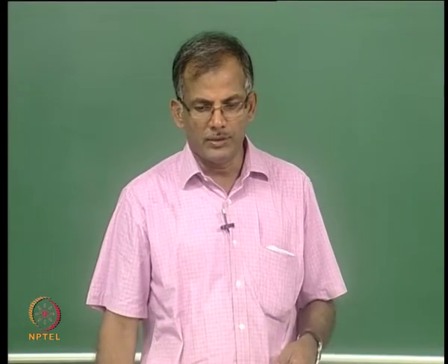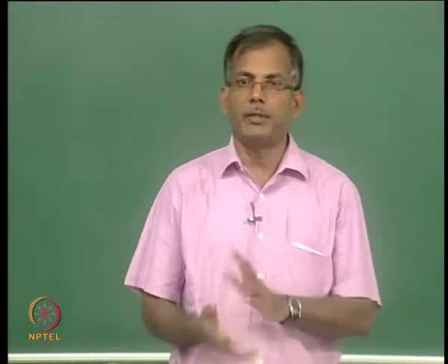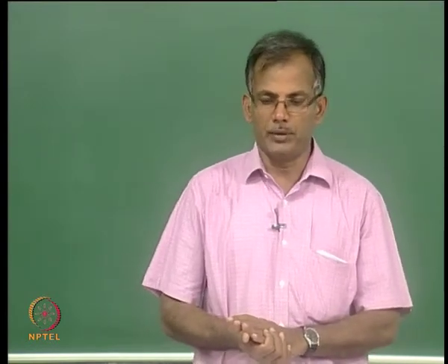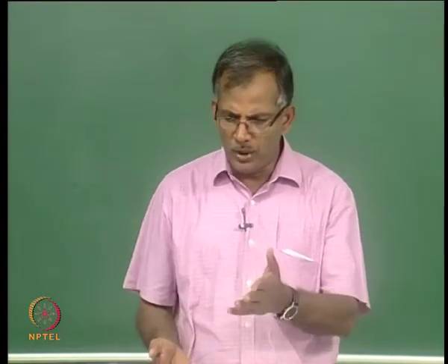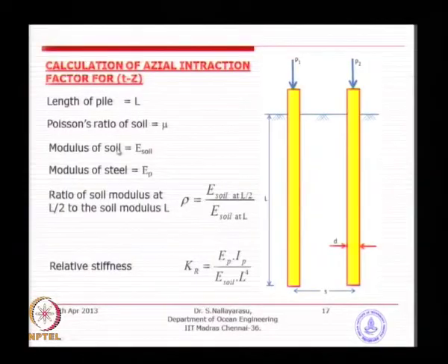We will continue with the effect of axial load on this pile because of the pile group effect. So, the procedure to calculate, if you have multi-layered soil, what we really need to worry about is the calculation of average properties for the modulus value. That is where the whole issue is.